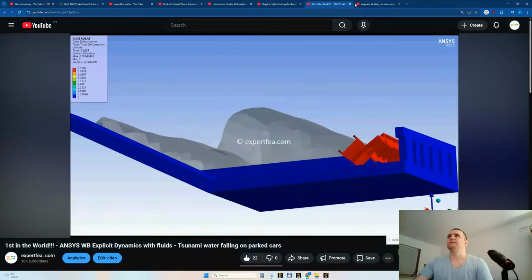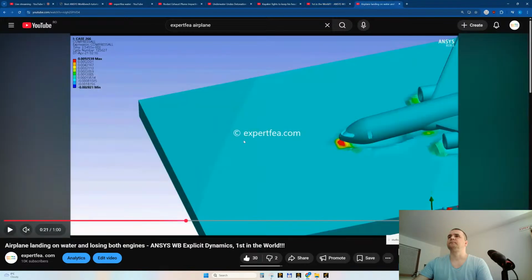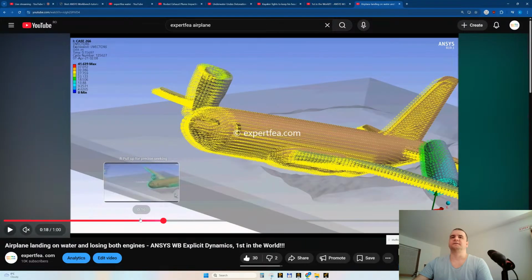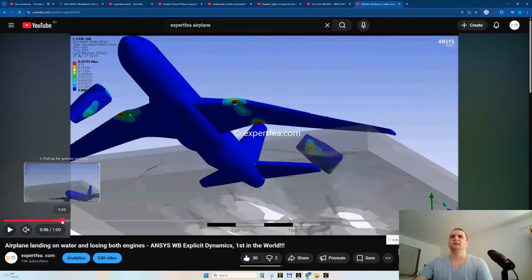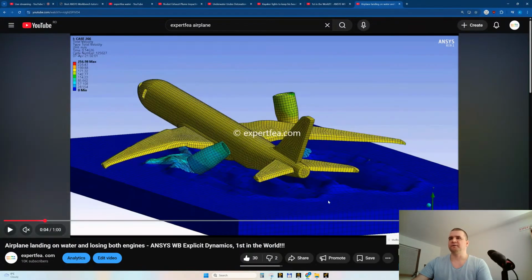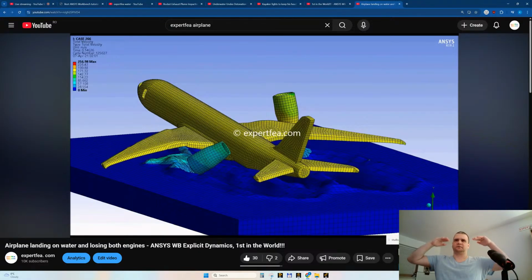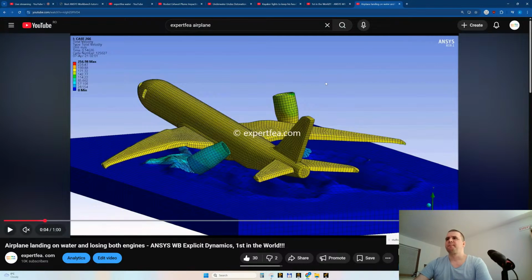In the simulation, the waves are higher because the upper limit of the Eulerian frame is higher. There is a bigger offset, okay? And the waves can exist until they hit the limit of the Eulerian frame. So yes, I will increase the top side of the Eulerian frame a little, to see if we have higher waves.